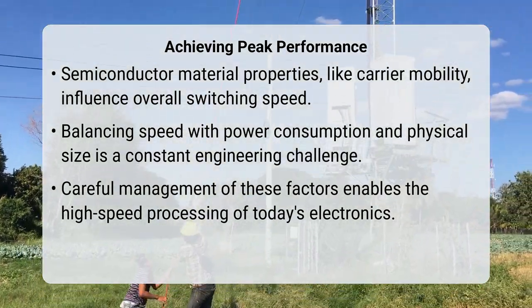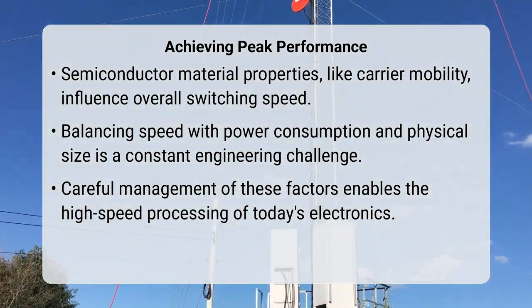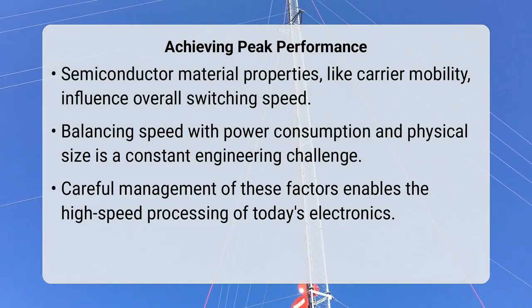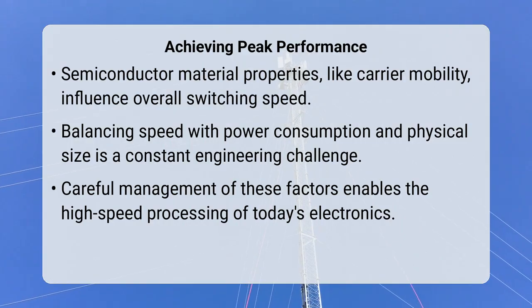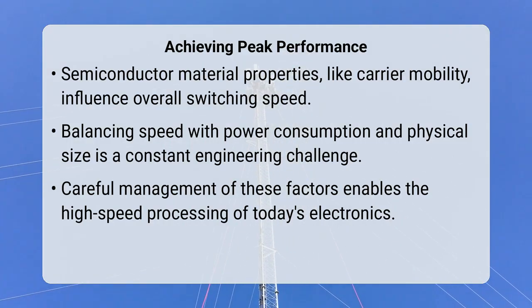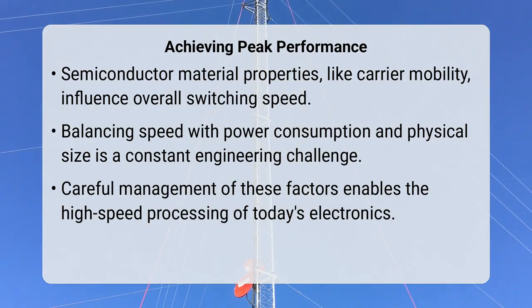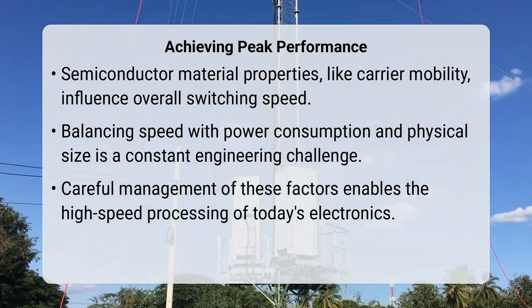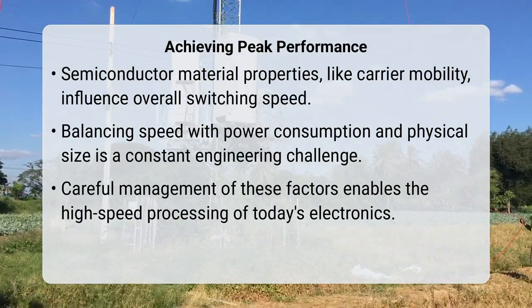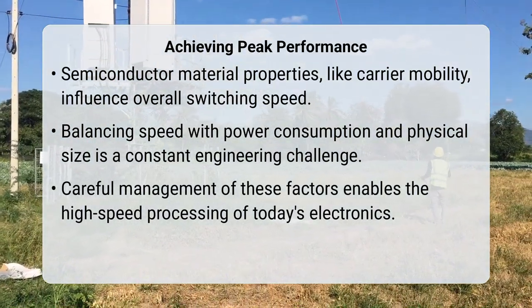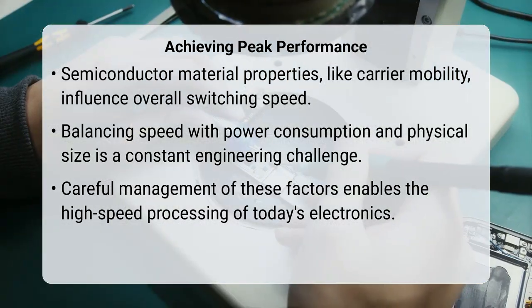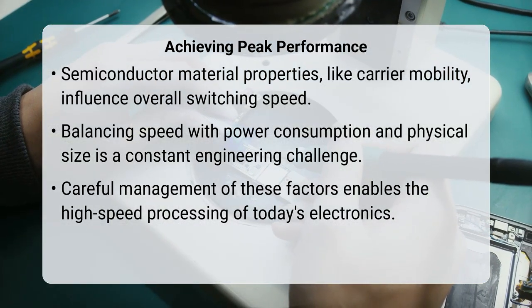Another strategy involves minimizing the external resistance and capacitance of the circuit connected to the transistor's output. Sometimes, selecting a different type of transistor altogether, like a specific type of field effect transistor known for high-speed operation, is the most effective approach. Understanding these underlying electrical principles allows for the design of faster, more efficient digital circuits.